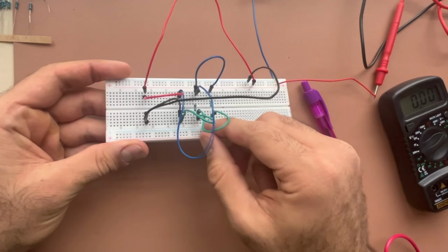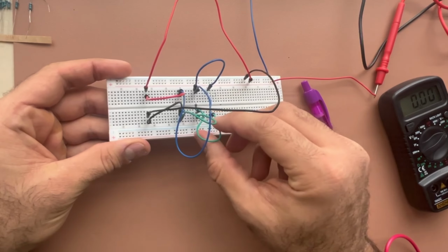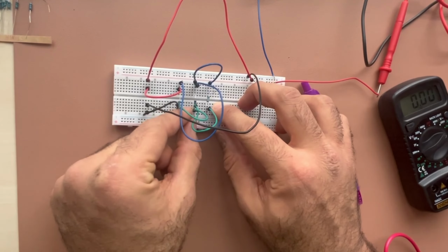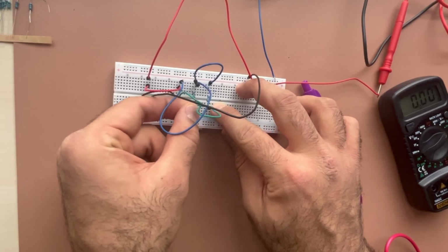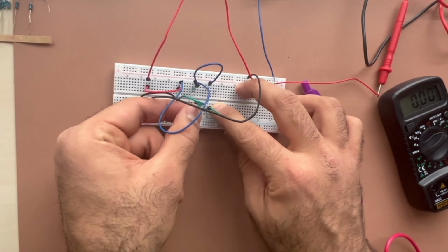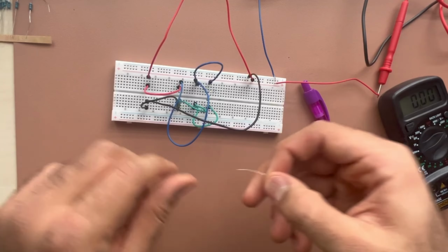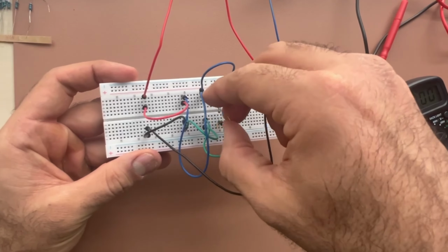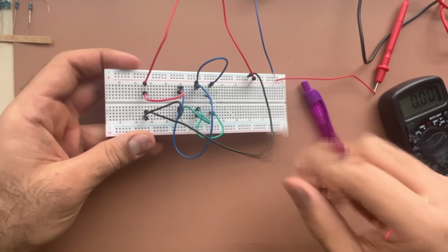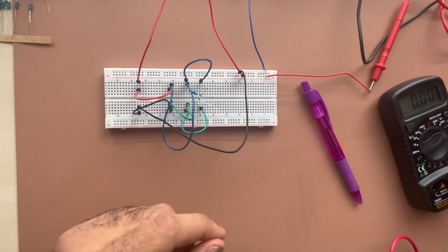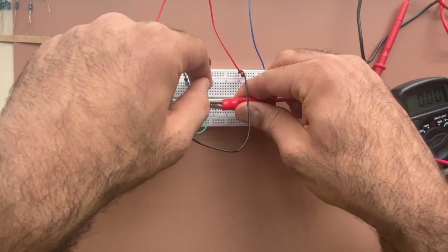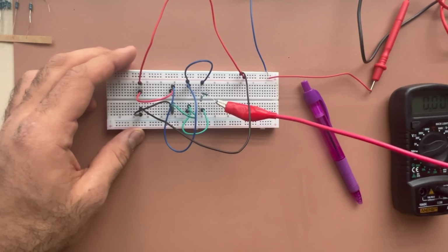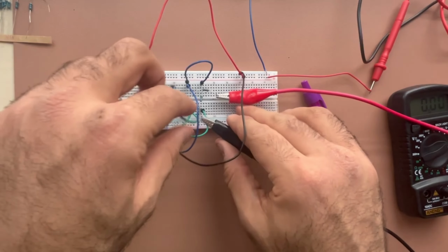So the one thing I'm going to do is that rather than disconnecting on the bottom section and then connecting it to another wire, I'm going to disconnect this leg itself. Because obviously, as we know, the current moves through this leg, right? So I'm going to do what? Oh, yeah, this is disconnected. I'm going to connect this guy in its place. Then I'm going to connect this one to the positive side of the ammeter, as you can see, like this. Then I'm going to connect this part, which is the negative side of my ammeter, to one of these wires.